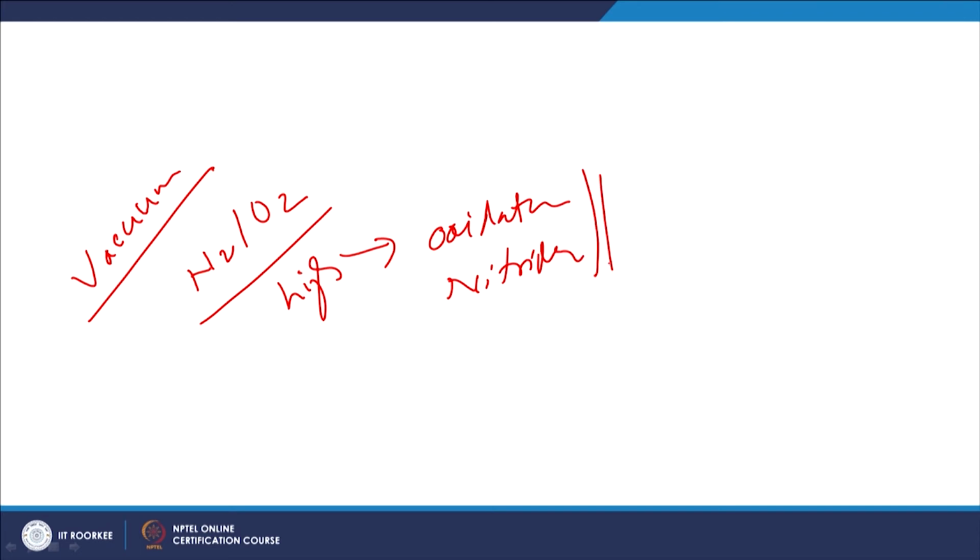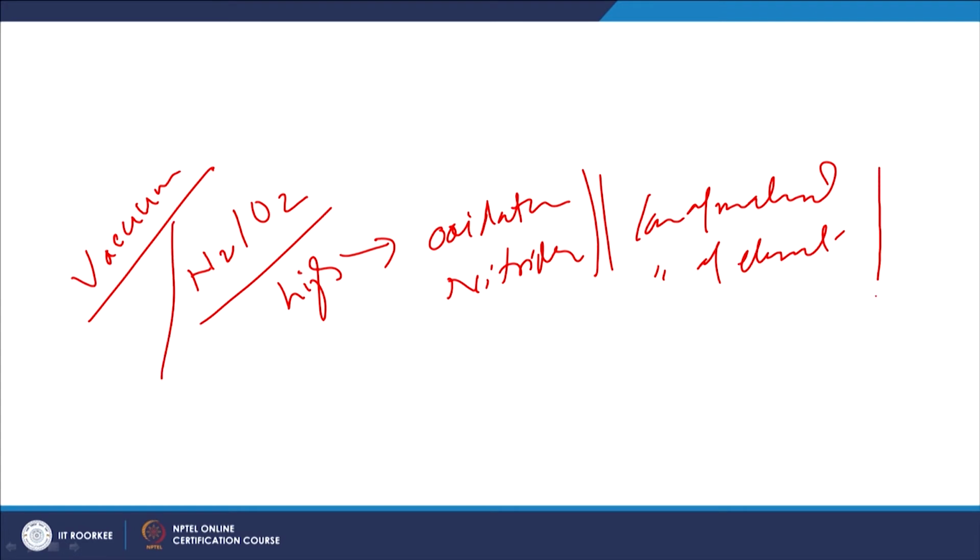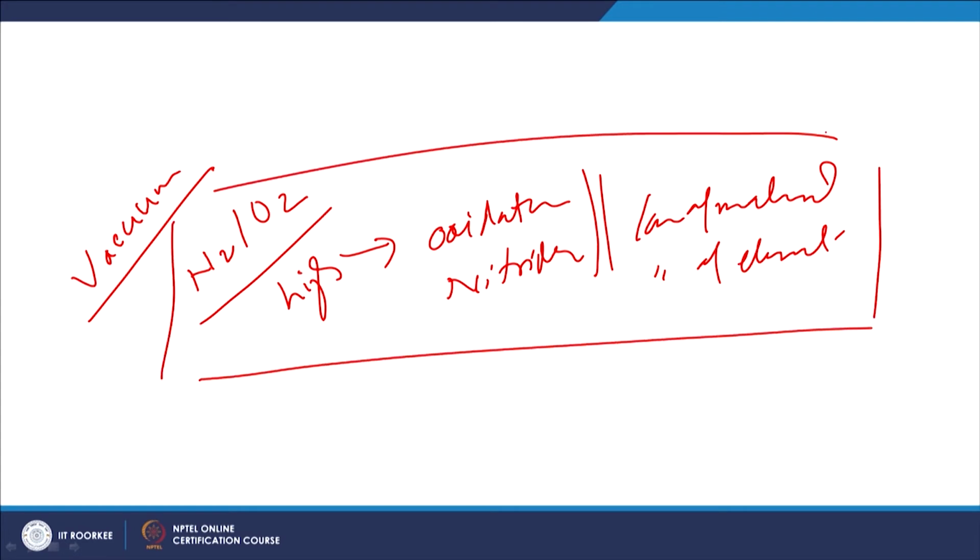So such kind of the oxidation and the nitride formation will be leading to the loss of material and loss of the elements from the functional surfaces which are being modified if the high temperature exposure is given under the ambient condition. But when the vacuum is used in this category of the processes, these gases are eliminated from the vacuum chamber. So despite use of the high temperature, absence of these gases doesn't cause any loss of the material or the elements due to the oxidation or nitride formation at the surface because of the vacuum.